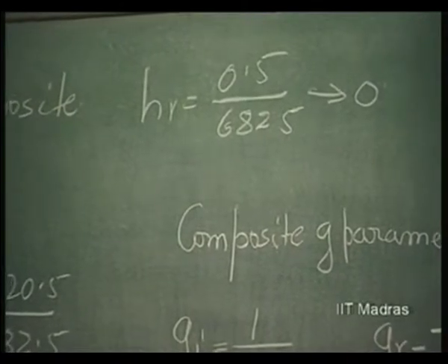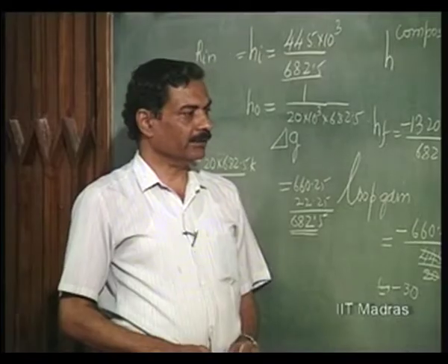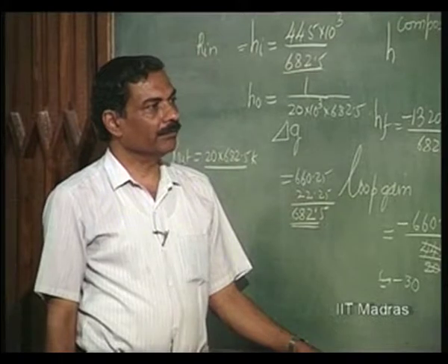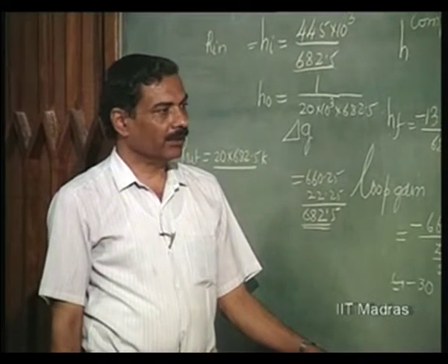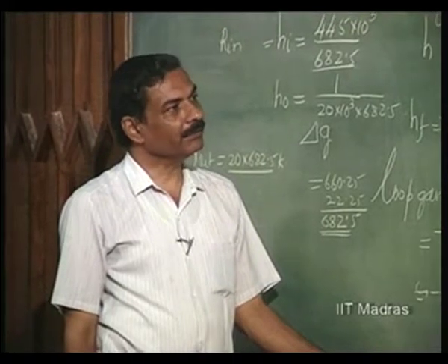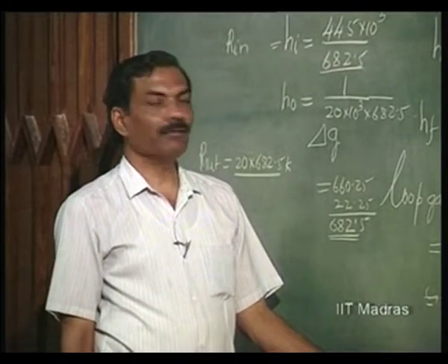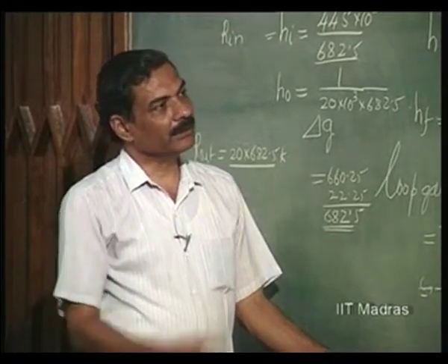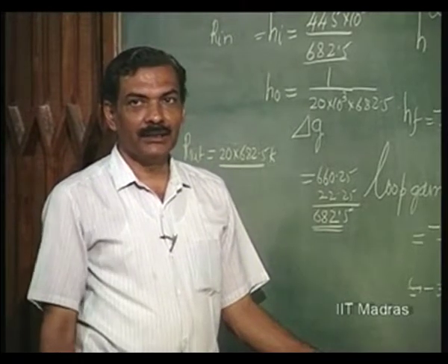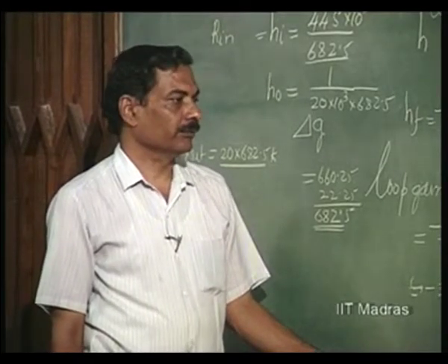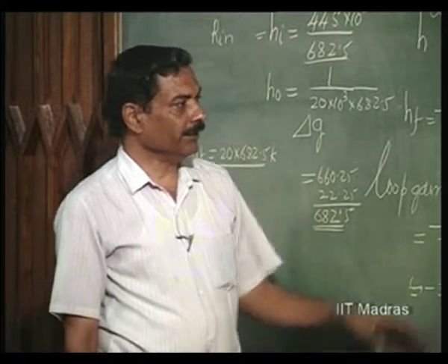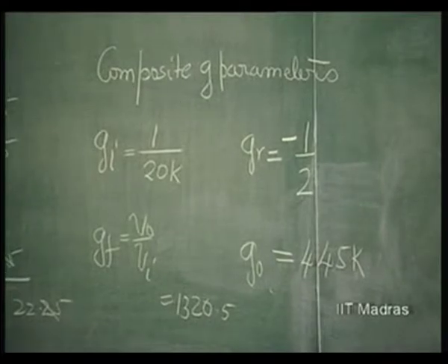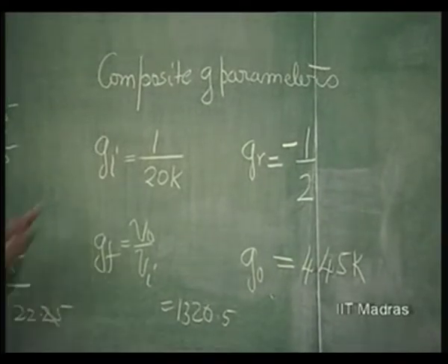So, this is how we can analyze a given circuit with negative feedback and conclude very quickly, without even doing any evaluation, that the forward transfer parameter is very nearly equal to 1 over the reverse transfer parameter of the feedback network. So, input impedance decreases, output impedance increases.